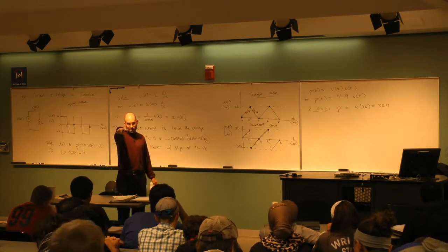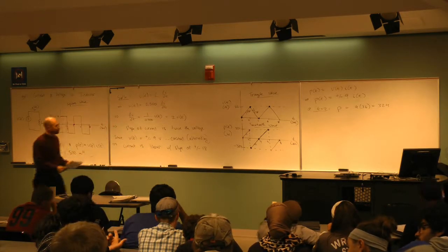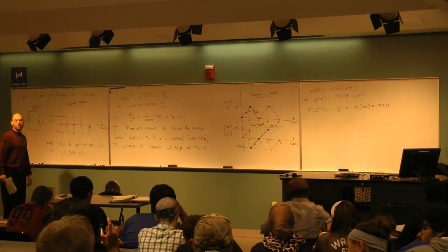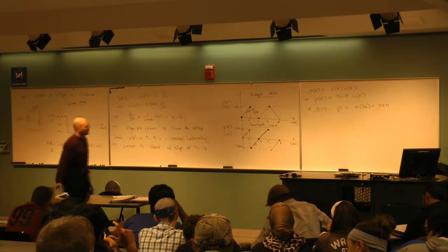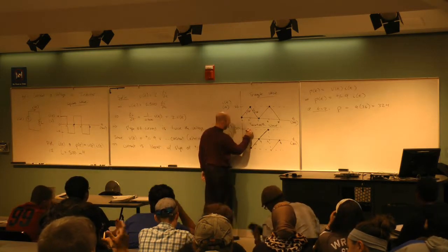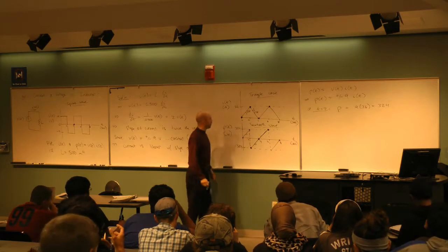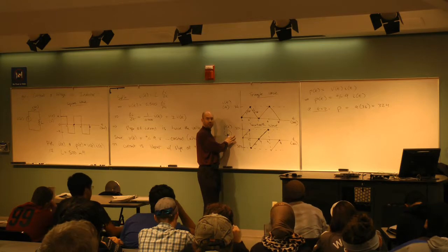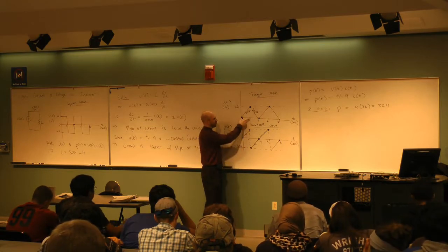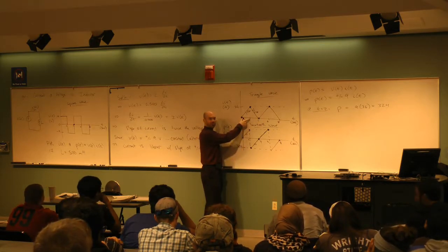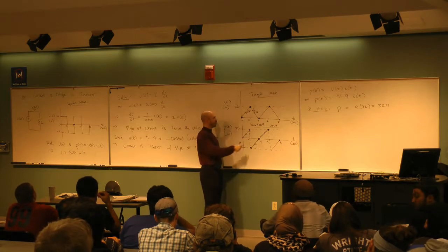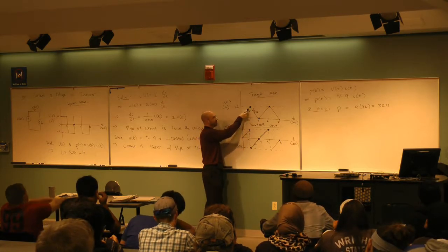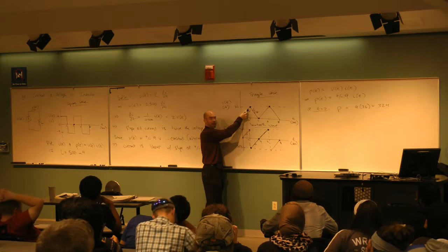Okay. Question over here. Just to get, why is the drop, why did it drop straight down? Yeah, why it drops straight down here? So what I'm doing is saying that by definition the power is the voltage times the current. So in the first interval, I've got a voltage of +9, the graph behind me. So I just take the current graph, which is this line, and I multiply it by 9.